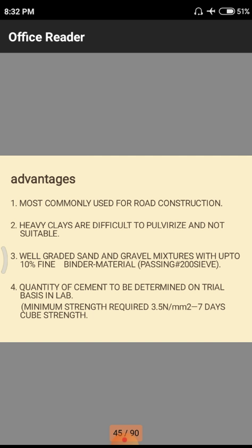Take a particular quantity of material and add 1% of cement, then 2%, 3%, and so on up to 10%. At which percentage we get good strength parameters, we have to observe.